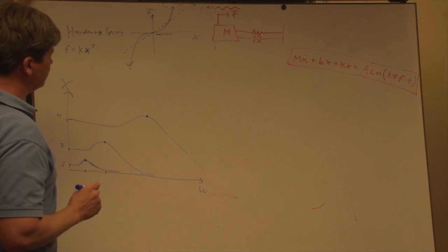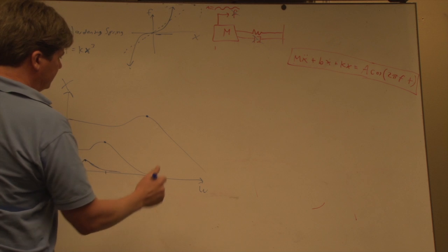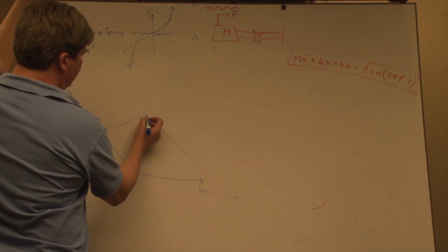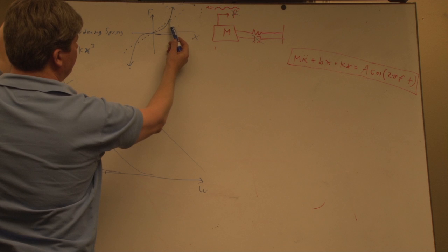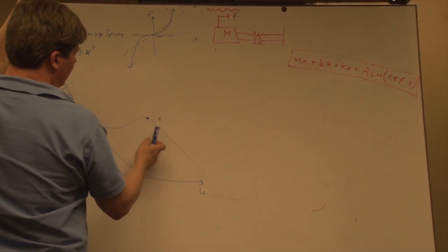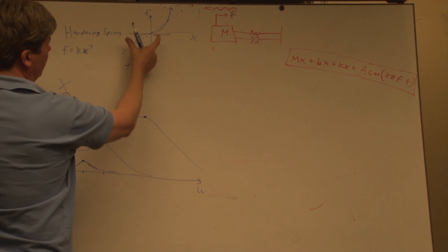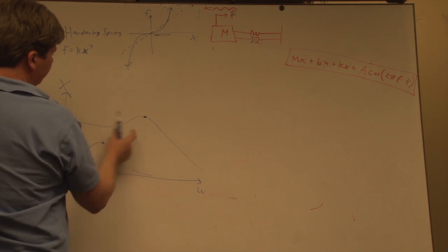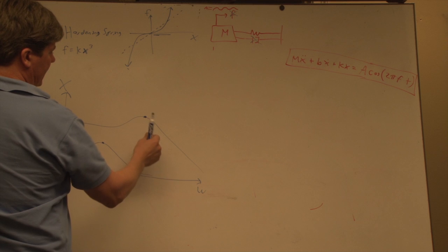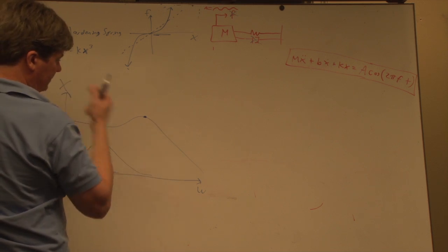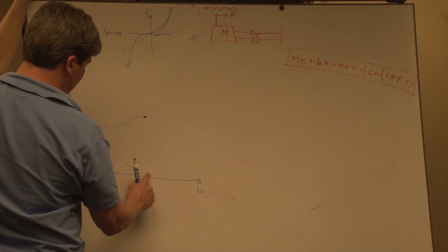Now, what happens is, in order to oscillate at a higher frequency than where your resonant point is, you actually have to get to a higher amplitude, right? But if you're driving this thing at a smallish amplitude, and you start going at a higher frequency, that frequency cannot sustain the oscillation, and you don't actually get these nice down curves.